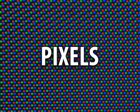The construction of a color CRT monitor is different from a simple CRT display. It has 3 electron guns or beams, each individually controlled by its video signal. The phosphor dot on the glass surface comprises 3 closely spaced color pixels, red, green and blue. Each electron beam falls on its respective dot and generates the respective color. When all 3 beams fall on all 3 dots with equal intensity, then white light is produced.